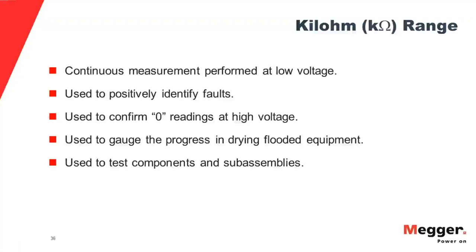And also, a lot of times components and subassemblies have lower insulation values because they're going to be buried inside a bigger piece of equipment where there is other insulation to protect the operator from ground. So the subassembly only needs to meet performance requirements, and they can be lower.